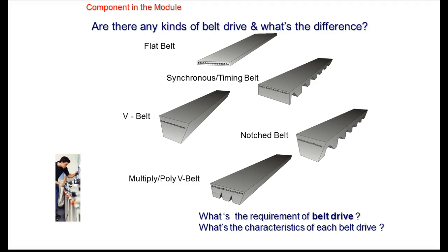Most of your belts slip, and this is one of the things that it iterated. With a chain drive, if something happens and the system stalls, something's going to burn up or the chain's going to break. On the belt drive system, though, if something stalls, then the belt just usually slips. So if you try to get more torque out of it than the belt's designed to handle, the belt just starts slipping, right? You understand that? Which is another big advantage.